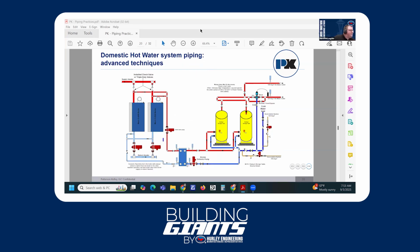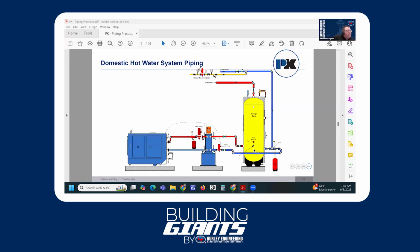So here, this is the same system. It's just showing a more complex piping arrangement. When we have multiple boilers, we've got to manifold things on both the boiler side and the domestic storage tank side as well. So this is still labeled as indirect heating. And there's confusion on those terms sometimes, right? So this is a volume storage tank for water, but this is an indirect heating application.